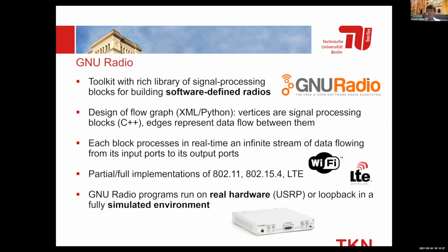And finally, the most important thing I would also say about GNU Radio is that you have the option to run your radio program either on real hardware, so you use some USRP, and then you can do over-the-air transmission, or you run it in loopback in a fully simulated environment. That means the wireless channel is also fully simulated in software.